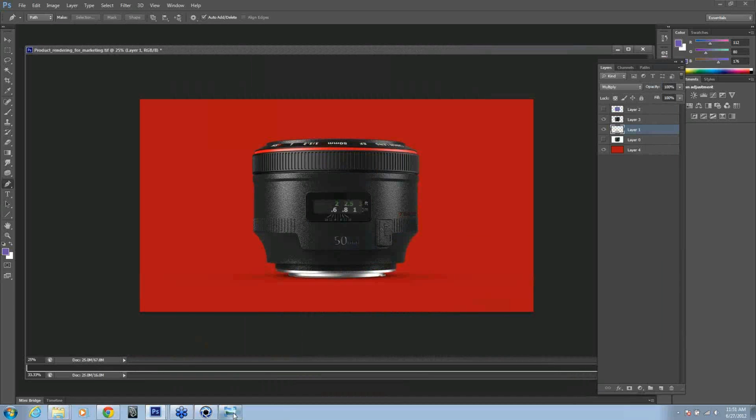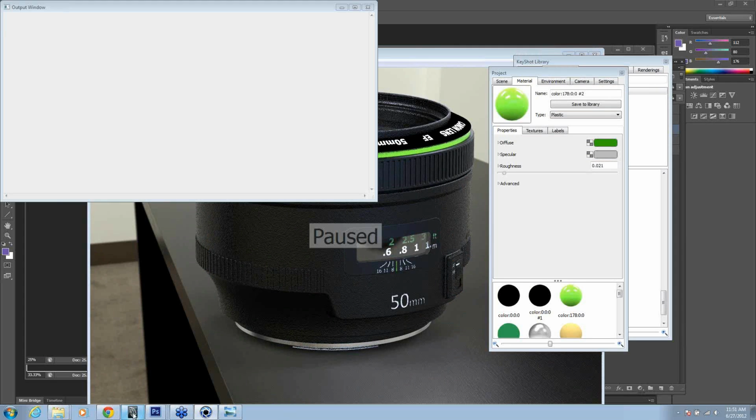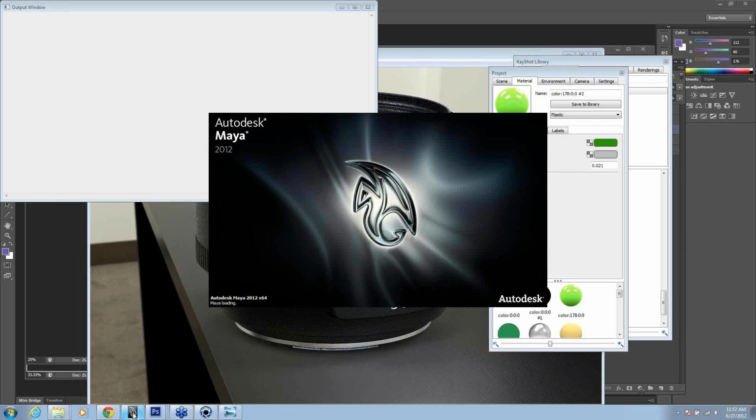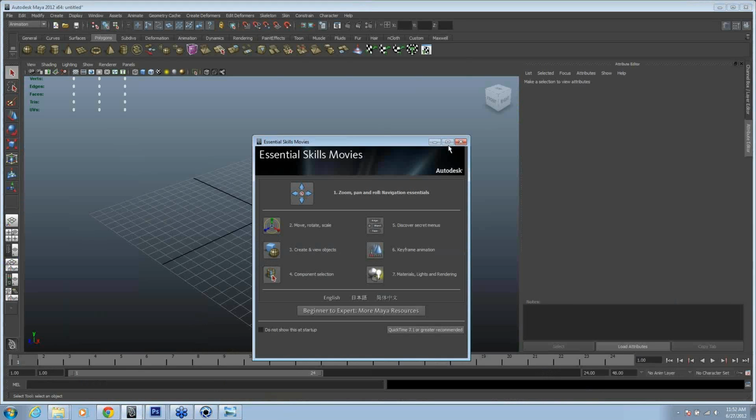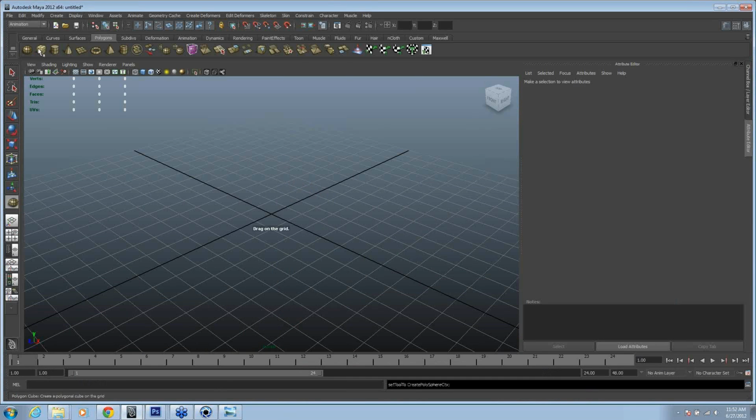This one's from Mike. He's asking, when it comes to transparent objects, for example, clear plastic, could you maybe touch briefly on importing the model and what attributes should be set? Sure, absolutely. Let me create an example here to kind of better explain transparent materials. It's very important that these are modeled correctly to be able to be rendered correctly. The important thing is that whatever model you create needs to have thickness.